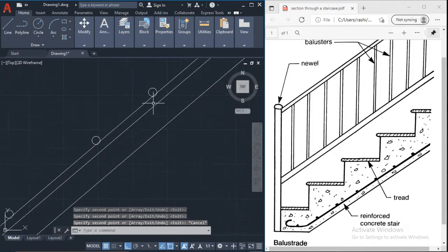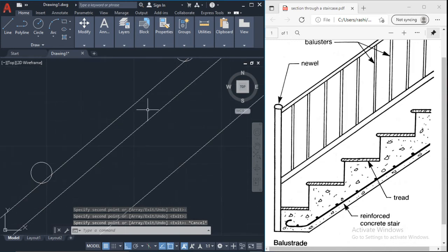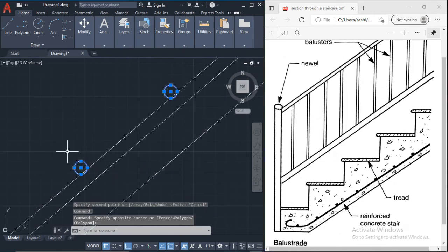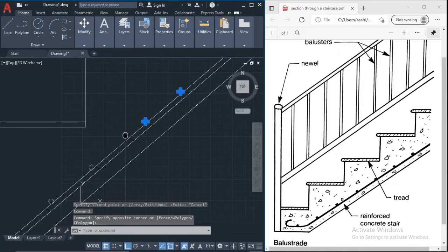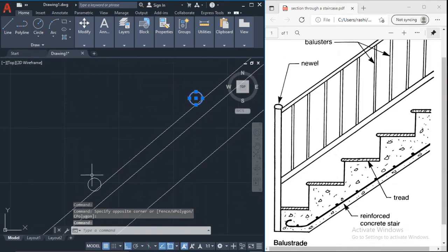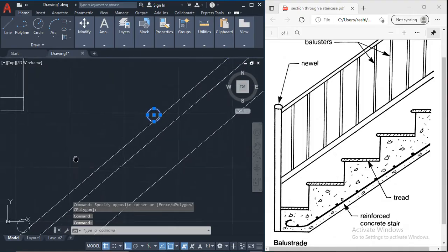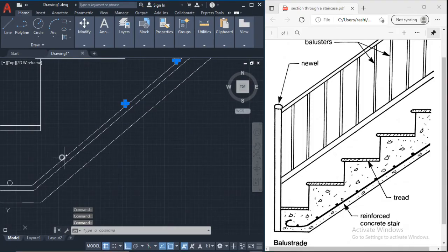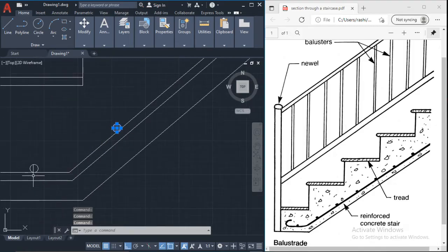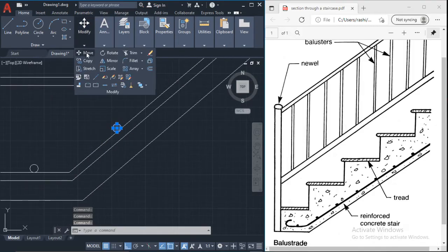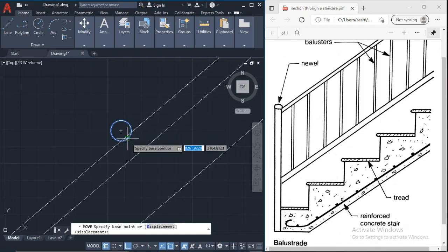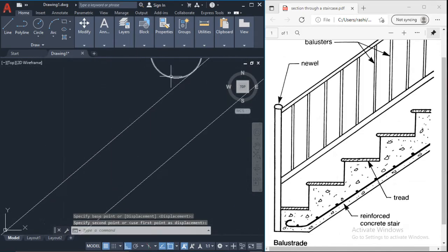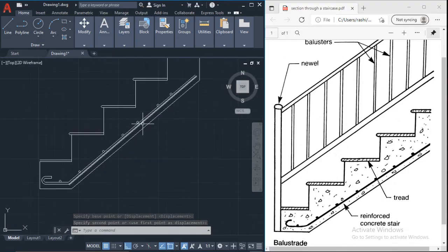All right, nice. So we have that, but as you can see, that is not 100% correct. A bit of it goes into the next rebar, so we need to bring these circles out a bit, and we can do that by doing this. Just need to have tangent turned on in Object Snap. So you just need to turn on tangent. This one is already good, so I don't need to change that one. So I can just move this from the tangent here, and then move it up to the line, and now they will all be right on the line.